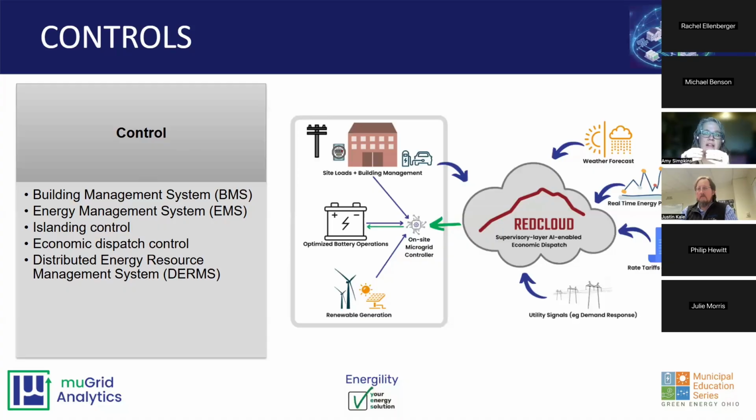That is usually a bit of software or computing that's on board the battery that helps monitor the battery's temperature and voltage and balancing between the cells. Normally, you as a facility manager will never see that. You'll really never see what the BMS is doing. But again, the BMS is working with the EMS to say, hey, here's what I can do with my current conditions in the battery.